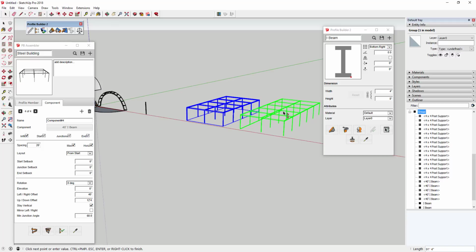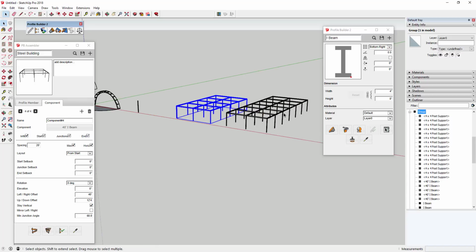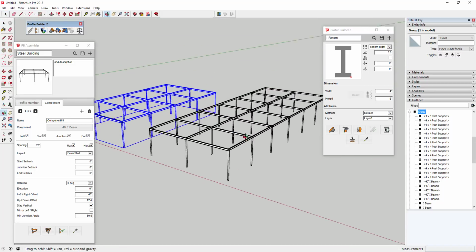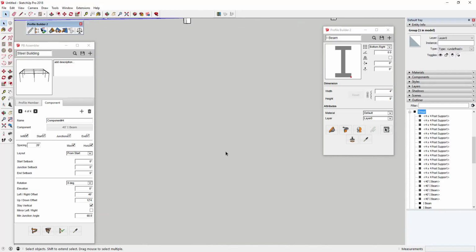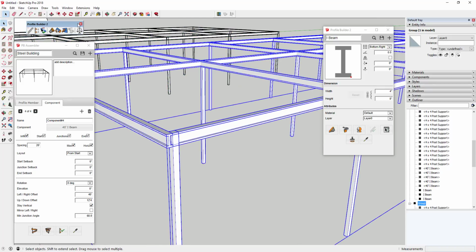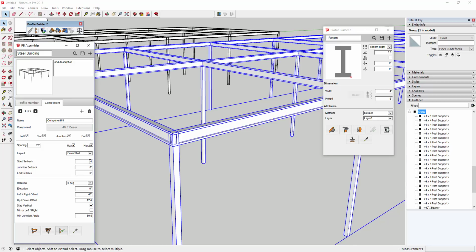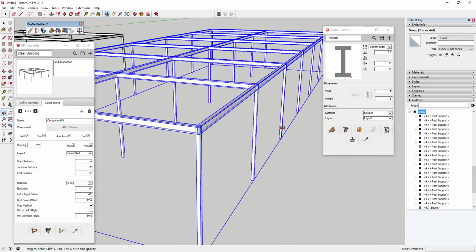And you can see how now I can generate a building with structural steel framing in here that automatically infills with the spacing of whatever I set. So there is some setup involved, but you can see how once you get this kind of figured out, this gets pretty easy to do. And the one thing you'd probably need to do now that I look at this, and you need to get pretty good at just coming in here and updating things just by looking at it. So in this case, I'm off by about 4 inches. So probably I'd need to give it a start setback of 4 inches. And you can see how when I do a 4-inch start setback and I click the update button, this moves this over by 4 inches, and now all of this lines up.